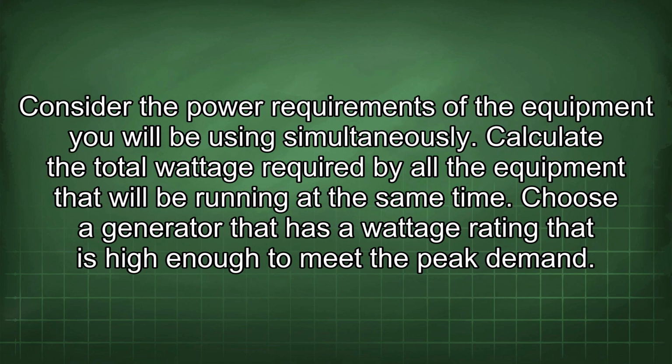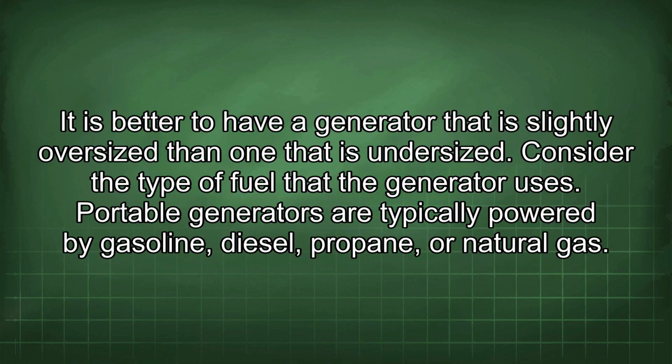Consider the power requirements of the equipment you will be using simultaneously. Calculate the total wattage required by all the equipment that will be running at the same time. Choose a generator that has a wattage rating that is high enough to meet the peak demand. It is better to have a generator that is slightly oversized than one that is undersized.